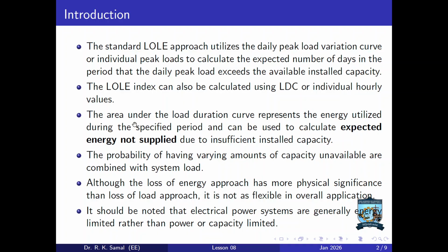The area under the load duration curve represents the energy utilized during the specified period and can be used to calculate the expected energy not supplied due to insufficient installed capacity. So while calculating loss of energy indices, our objective is to obtain how much energy is not supplied.